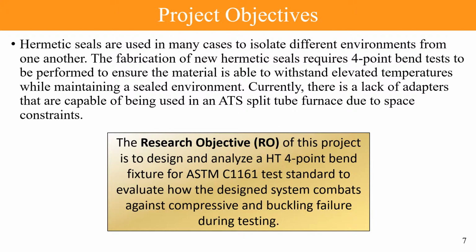Currently, there's a lack of miniature adapters that are capable of being used in an ATS split tube furnace due to the space constraints. So the research objective of this project is to design and analyze a high temperature 4-point bend fixture that's suitable for the ASTM standard, to evaluate how the designed system combats compressive and buckling failure during testing.